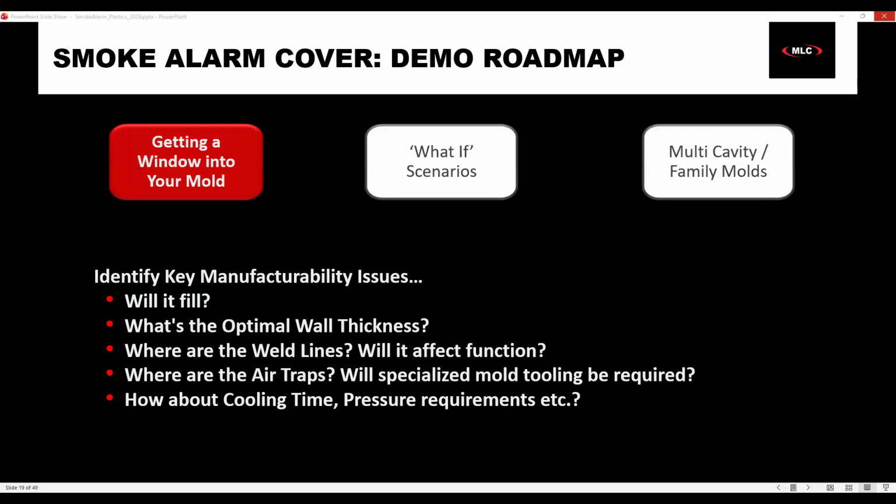The pack simulation is additional onto that. The pack simulation is at the end, when there is material that's already in the cavity and it started cooling down, the injection molding machine increases its pressure and forces the rest of the material into that cavity. And we get a lot more information with the combined fill and pack.